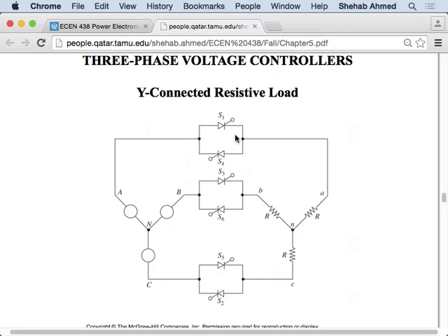If all these are diodes, it's like putting wires here, and then these are three balanced loads. If these are three balanced loads, I can connect this neutral here, and no current will actually flow. So I can take this point and connect it to this point. Now I have the phase A circuit looking like this. So across the phase A load, I have phase A voltage. Across the phase B load, I have phase B voltage. Across the phase C load, I have phase C voltage. That's the case for all diodes.